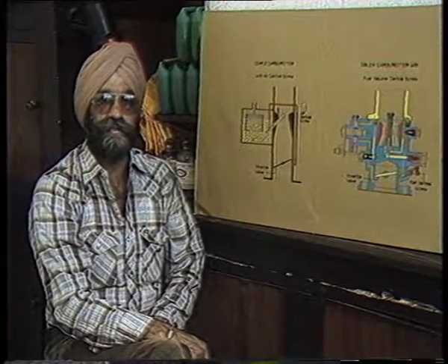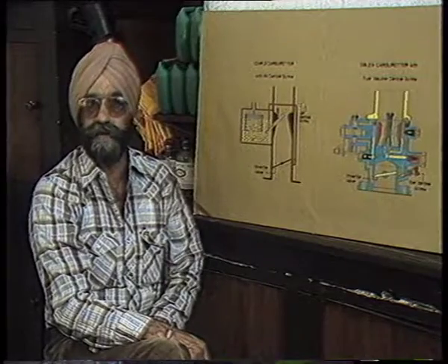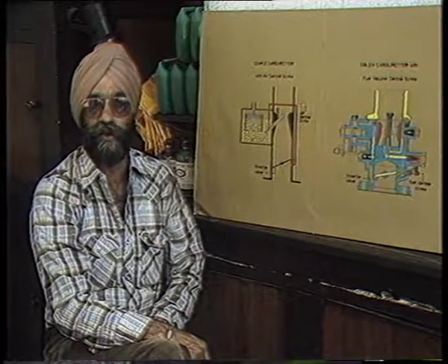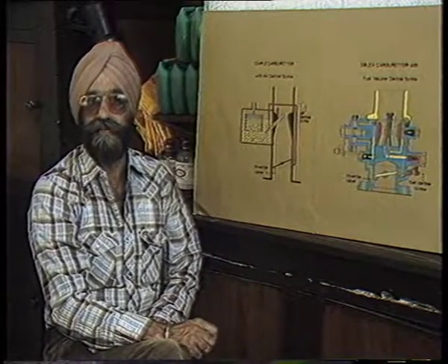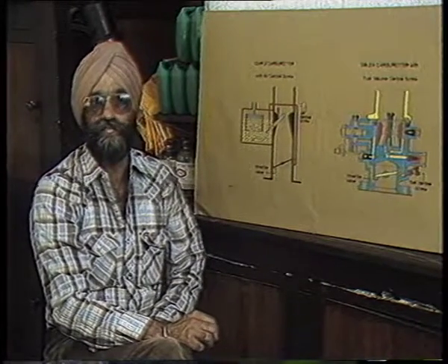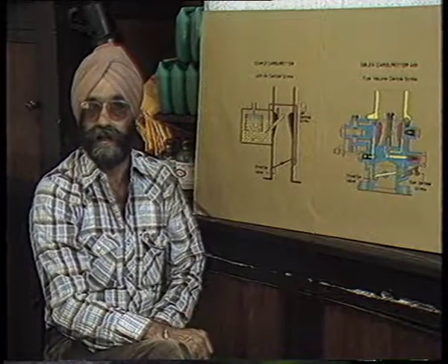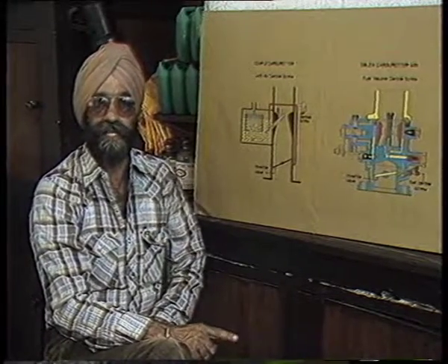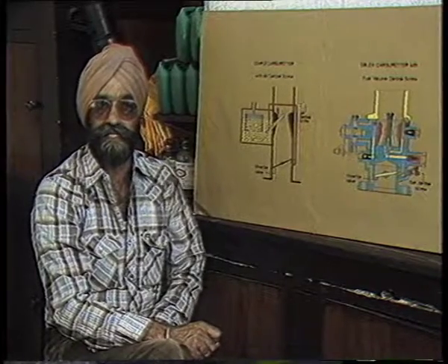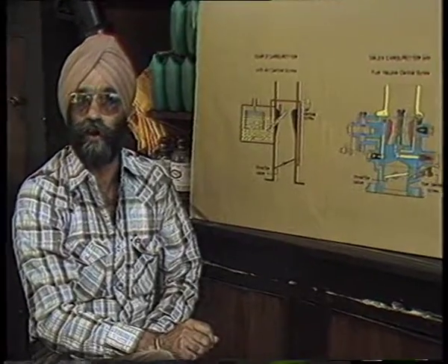All fixed Venturi carburetors employ some kind of idling system to deliver mixture feed to the engine at very small throttle openings. This system is necessary because at minute throttle openings, the Venturi itself does not generate sufficient vacuum to make the car idle. The idling mixture adjustment in fixed Venturi carburetors is done either with an air regulating screw or a volume control screw.